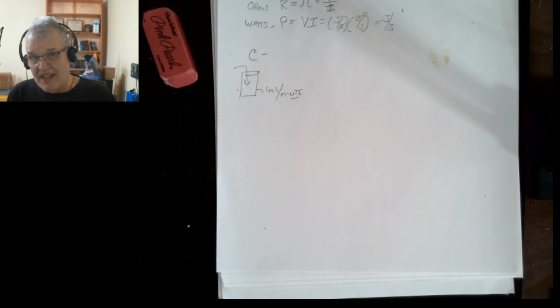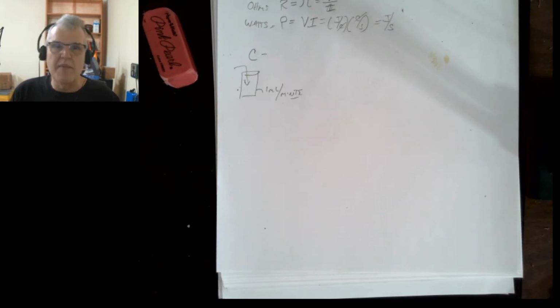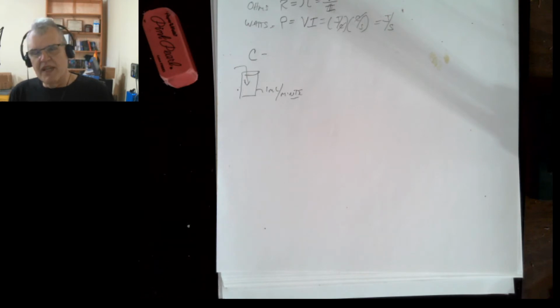Energy is given in watts, of course. So there's also an energy capacity that is given in watt hours. And watt hours, of course, would be calculated using the voltage, the nominal voltage. Really, to get the correct power and the correct capacity, you'd have to integrate underneath the curve from the discharge rate to what the actual potential was at each point along the way. But most people just use the nominal voltage.